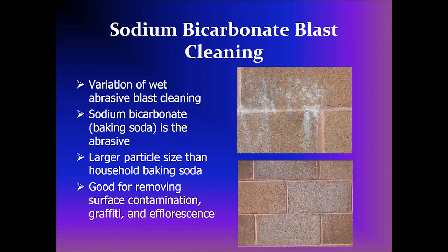There you see some lime deposits or efflorescence coming out of some integrally colored block on the top, and the bottom it was cleaned with sodium bicarbonate. But notice the risk here. While you did remove the deposits, you've taken some of the color out of the block. So again, do a test area for any of these methods to make sure that the end result is okay, that you're not creating other problems by trying to remove surface contamination or graffiti. But it can do a very effective job of cleaning, but in this case, because it was integrally colored, it actually took some of the color out of the block, which was not acceptable.